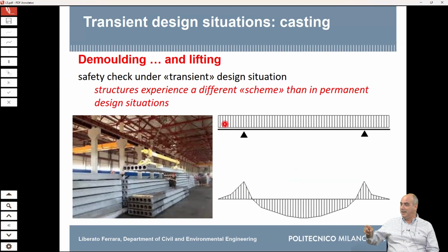Well, I saw in the diagrams you showed this morning that you draw the moment the opposite way. Well, we draw the moment on the side of the stretched fibers. But this element here, you see, is going to experience some negative bending moments. Most of the cases, your reinforcement is always on the bottom, sorry, you have to put something on the top to avoid excessive cracking. As we will see, it will be the day after tomorrow when we will see the design of pre-stressing.